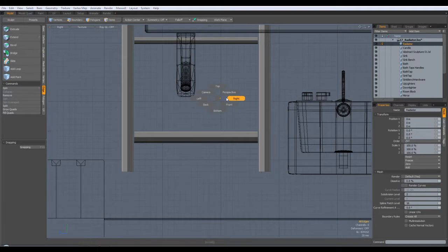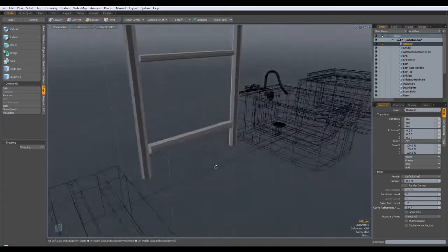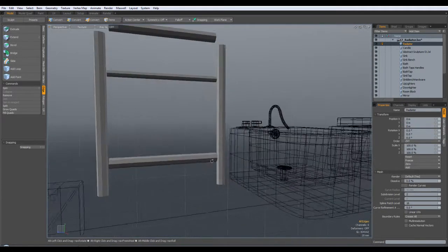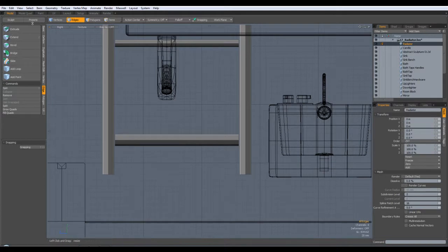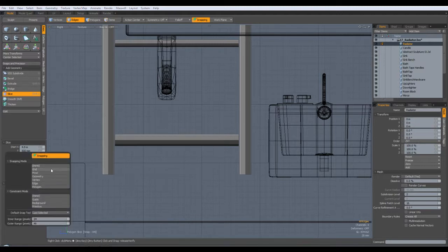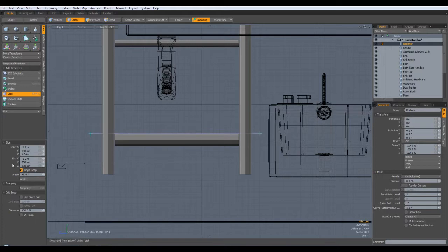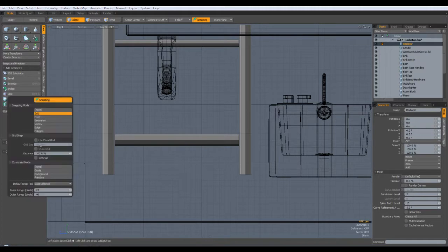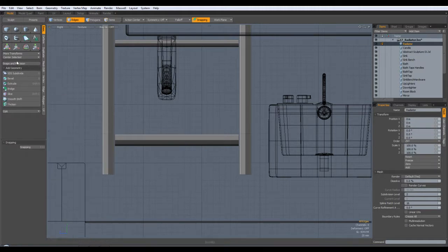It's going to be an easier bit for us to finish. So now we need to cut these. We'll start cutting these bits together. What I'm going to do is go over to Basic Tools, Slice. We'll turn the snapping grid on. I'm going to cut along there. Along there.